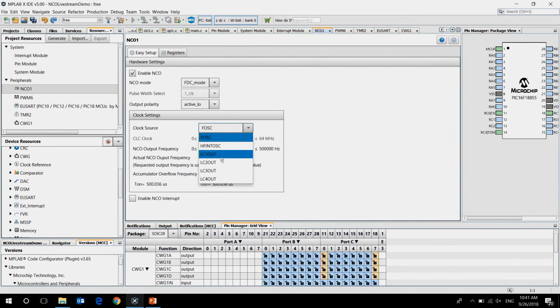And if you look at the other clock source on my screen here, if you're not familiar with the name, that's actually the CLC output. So, configurable logic cell. Remember, we talked about the CLC last episode. It's a logical output, so you can have all kinds of logical outputs feed into your NCO as your NCO clock, and that adds flexibility to your design. And create maybe a unique peripheral, kind of like what we're going to talk about in the next section.